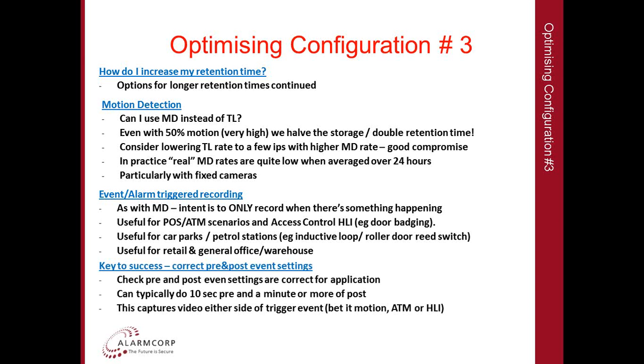Now the key to success is correct pre- and post-event settings. Check that the pre and post are correct for the application. Now typically most DVRs will do between 5 and 10 seconds pre-event and a minute or more post-event. Now this will capture video either side of the trigger event, be it motion, ATM or HLI interface.